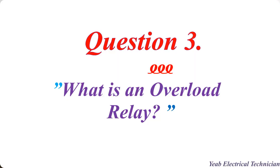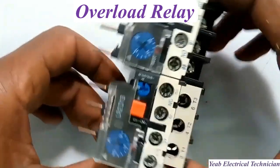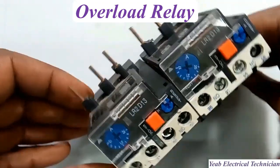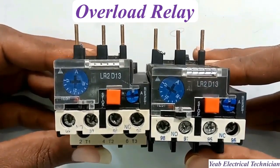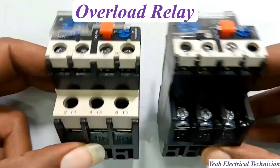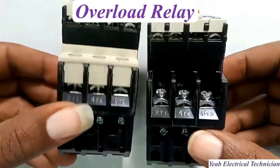The third question, what is an overload relay? An overload relay protects an electric motor and its component from damage caused by excessive current, which can lead to overheating. It does this by monitoring the motor's current draw and, if a continuous overload is detected, signaling a contactor to open the circuit and shut off power.